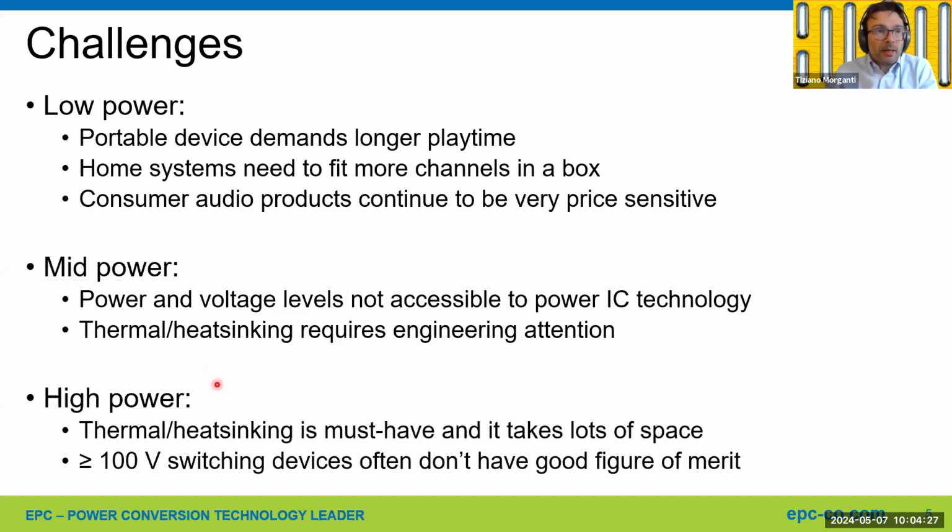For the high power market, we are talking above 400-500 watts up to a few kilowatts per channel. So this is the realm of pro audio amplifiers. It is even more important the heat sinking, and of course at this power level a heat sink is required, and often with forced air cooling. So it usually takes a lot of space.